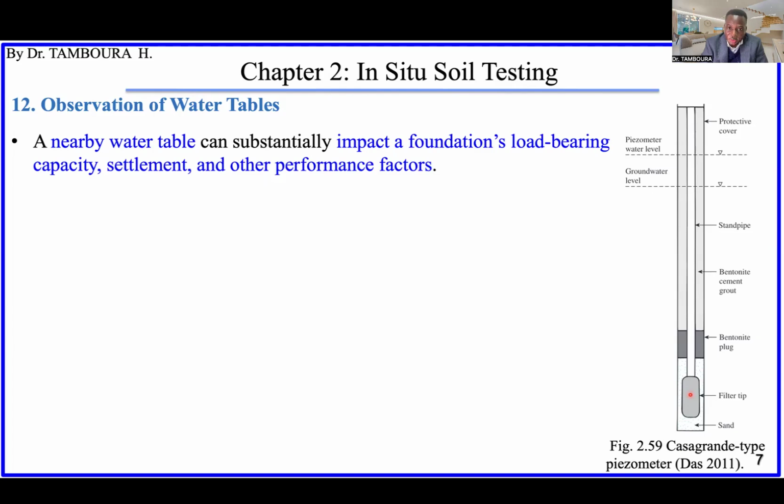Where is the water table located? So that we can predict the influence on the foundation, on the bearing capacity. It impacts the foundation load bearing capacity and also settlement and many other performance factors.